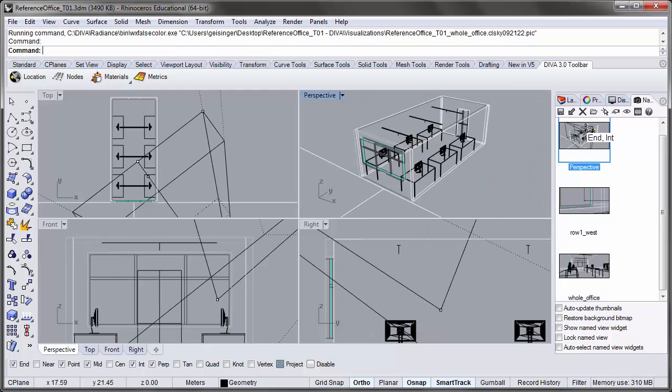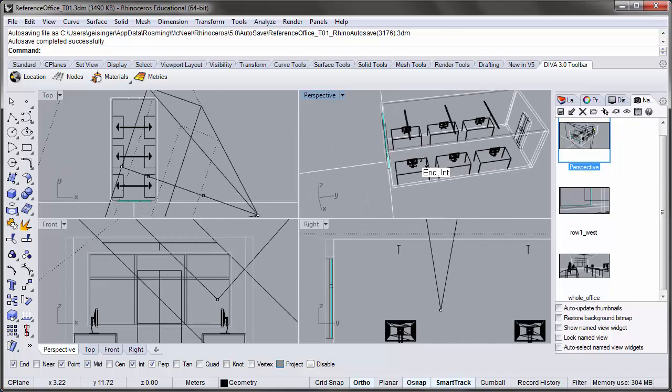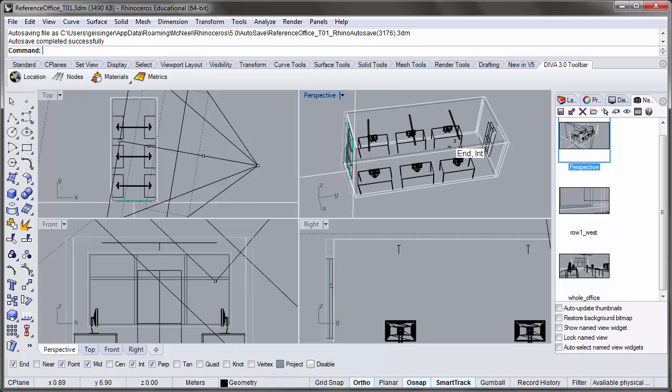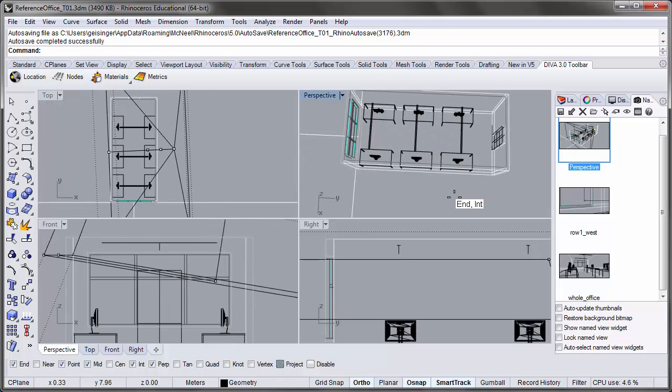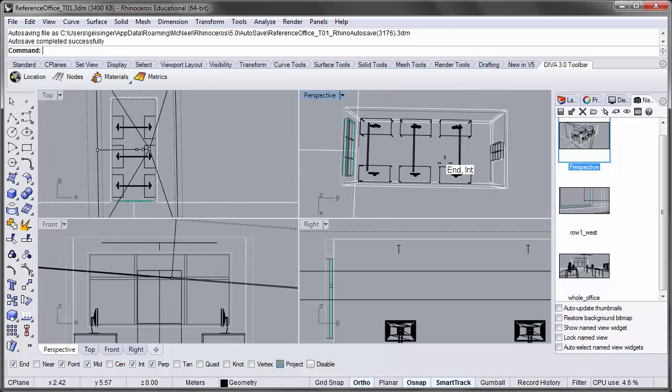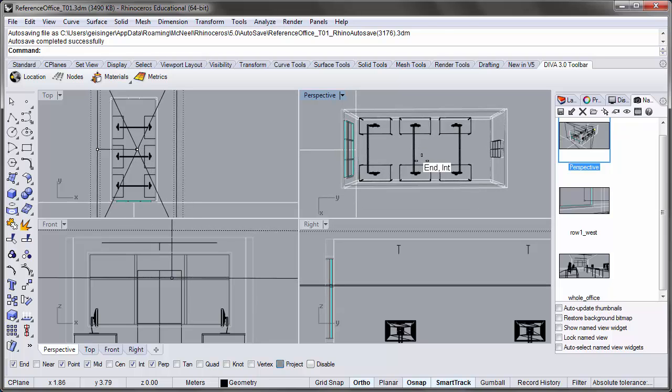And so I'll go ahead and double click on this perspective view, and I will use my mouse to situate the camera in such a way that it is looking straight down on the space, kind of like a plan perspective. So I will use the right mouse button, and shift to pan over, and position myself in a way that looks down at the space in plan.